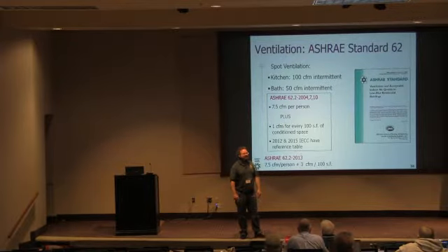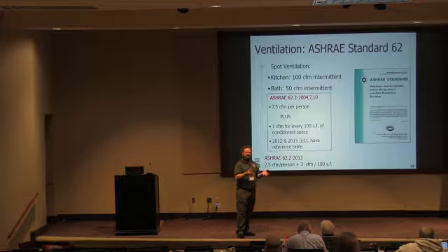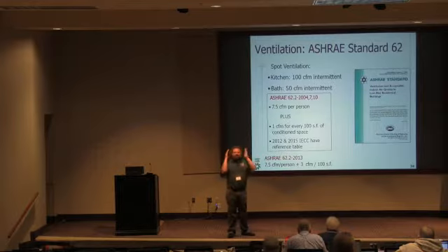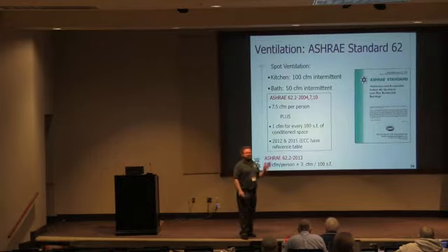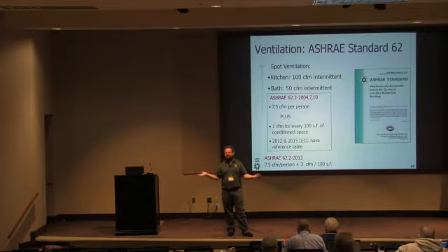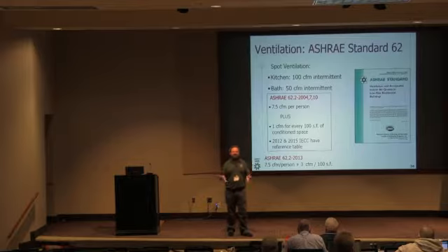Any other questions? It's crazy though, right? A lot of these things that go on in houses are really simple to fix, but people come in with blinders. Like, I do one thing. I put in exhaust ventilation. So you've got a comfort problem. I'm going to put in a bigger fan. But if your exhaust is dumping into your attic, the bigger fan doesn't fix the humidity problem that the house is experiencing.